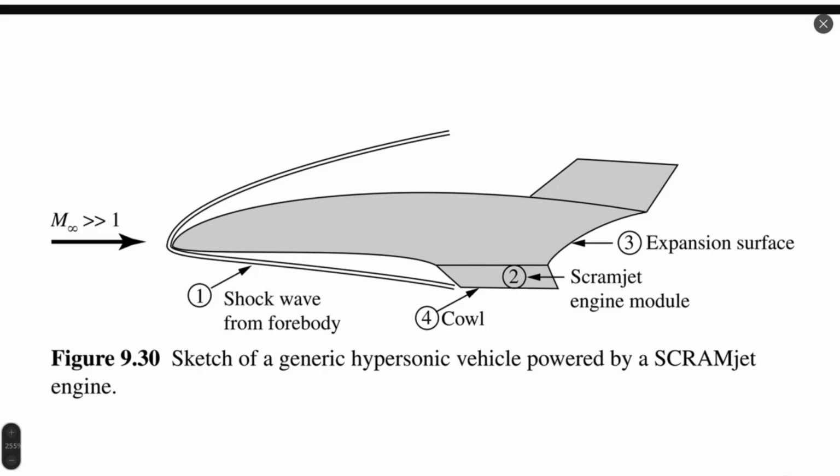We have a highly fast flow, highly supersonic or hypersonic, that creates a shock wave around the body. This shock wave is extremely close to the body, and it's usually an oblique shock wave. After this type of shock wave, we always have supersonic flow.